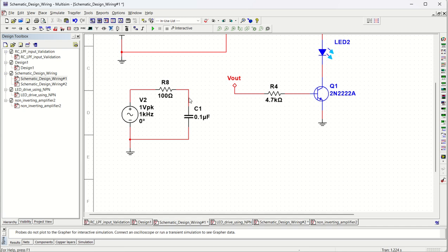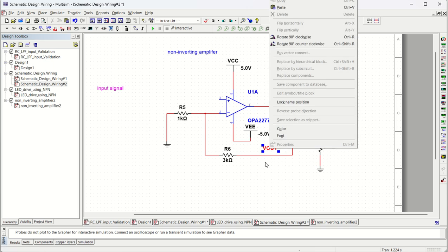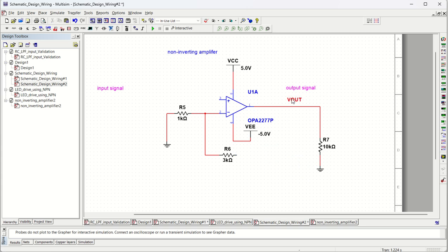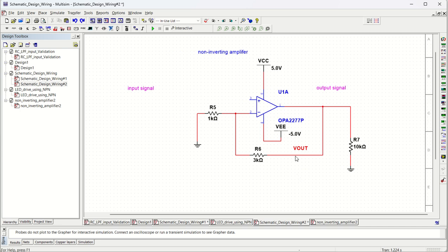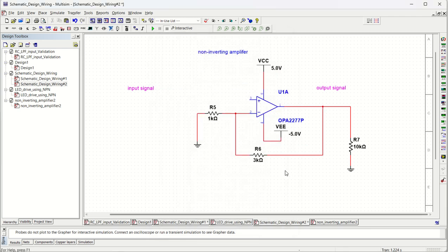Now I am going to connect an off-page connector here, and that output will be fed to the second page input. Okay, and this is how it will get multiplied. Understood? So I'll just remove this name also. Let's say delete it, or Control Z, and then come back here, properties, net name, you delete it. Okay, so no net name is there by default.